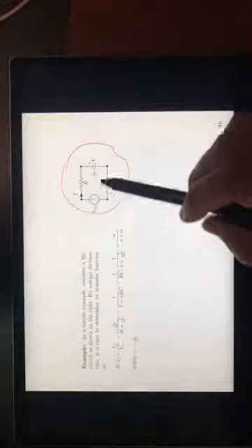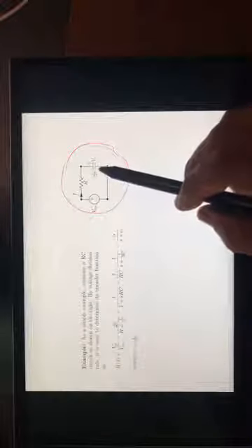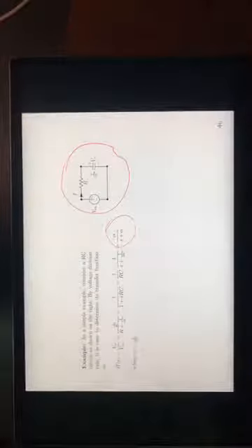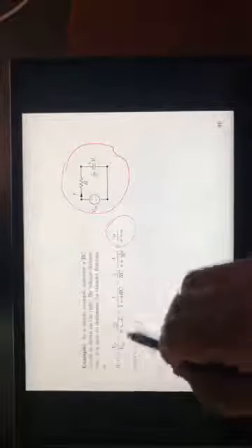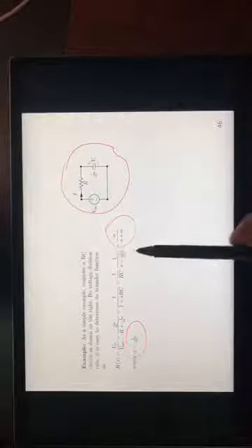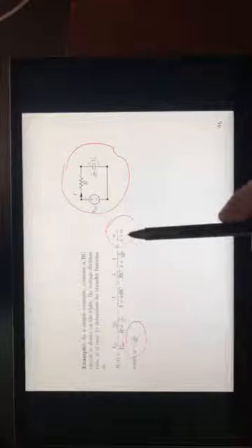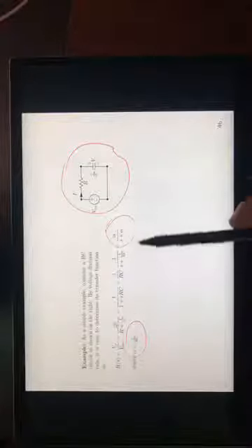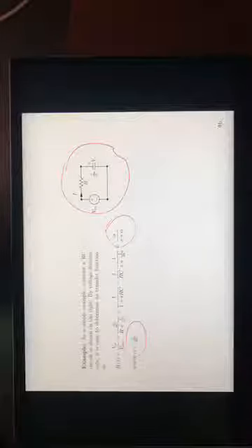There is a resistor and a capacitor, and this transfer function is alpha over s plus alpha, and alpha value is 1 over RC. So if you are given an expression or a circuit, you can convert it into a transfer function. A transfer function means now you replace s with 1 minus z inverse over 1 plus z inverse, and you get a difference equation. You implement the difference equation and you are done with this.